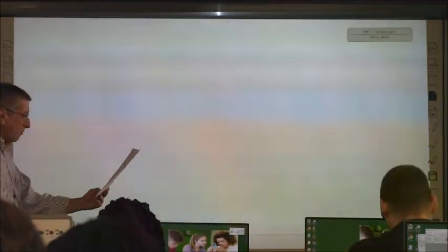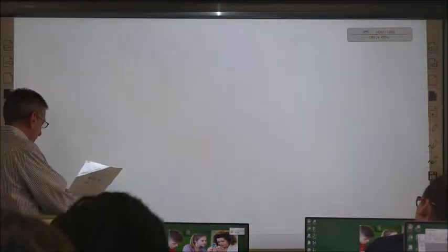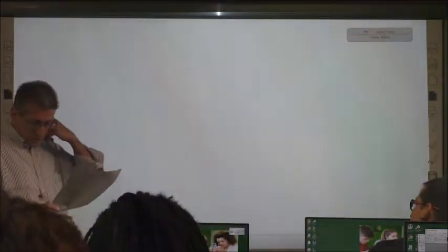A normally open proximity switch is programmed into your PLC logic as an XIO instruction, and then the proximity switch is made. So it's normally open. What will be the state of the instruction in the logic? Whenever you're in doubt, draw this thing.